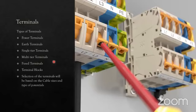So in general in case of PLC, we use it for the inputs, like if we have digital inputs or analog inputs, because for the inputs, power is coming from the outside of the panel. But for the outputs, the fuse terminal does not require much. So for the digital inputs and for the analog inputs, we use fuse terminals. In between the instruments and the PLC connection points, we use fuse terminals.